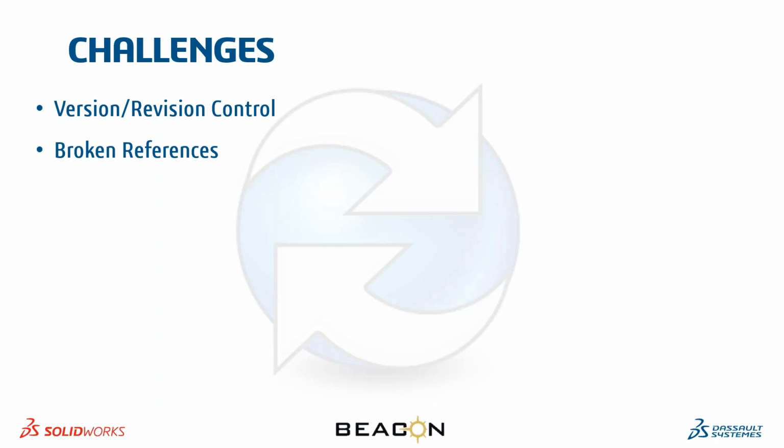Next, another big problem is broken references. Someone uses a part in a design or an assembly, and while saving, they save it with a different name, or someone moves it from one folder to another without updating the references. That causes the loss of references between the assembly and the parts, which, when you're releasing the whole assembly, means you will have to rework the lost references, or spend time searching, just like we saw in the video, where you have to go through a lot of data and search for files, and you may not find them at the end of the day.